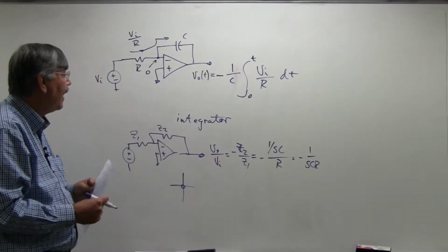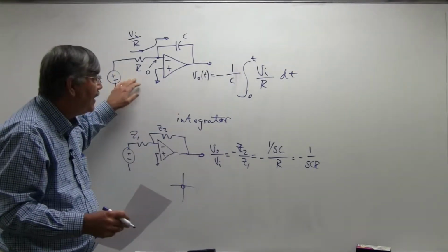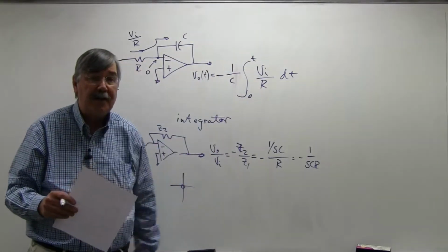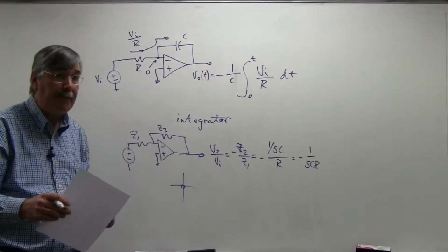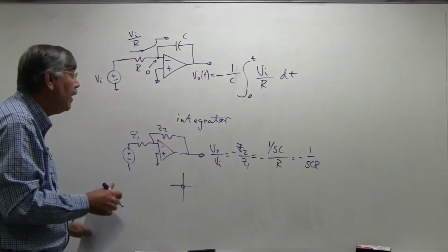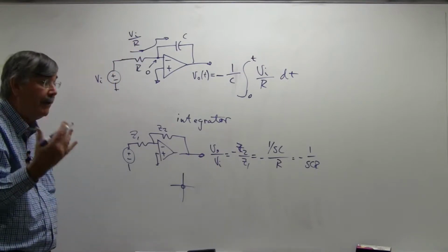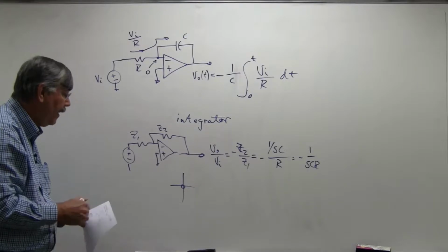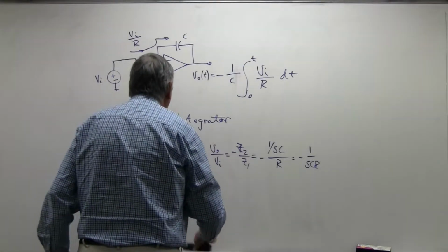So what does that mean in our case? It means if you've got any input, like a DC input or something like that, and we just let this thing go, it's going to integrate out to infinity. In a practical matter, it would integrate until the op-amp can't be considered ideal anymore. So if it's got a bounded input, it can get an unbounded output. So that's one definition of instability, and this thing would have it. So that's an interesting fact. So how could we make it stable?